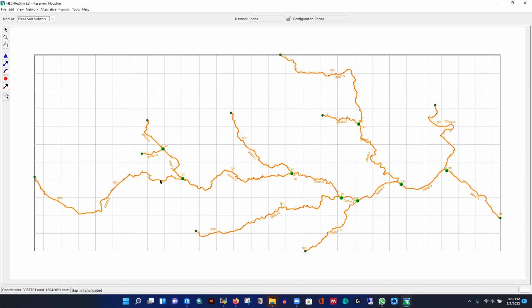So this water will be directly transferred here and transported there as it is. If you have a long river, then this amount won't be there. It will take time to go there, and it will lose some amount of water. It will be superimposing with this one at a later time, so the peak will be changed. So that's why you need to use a routing mechanism.